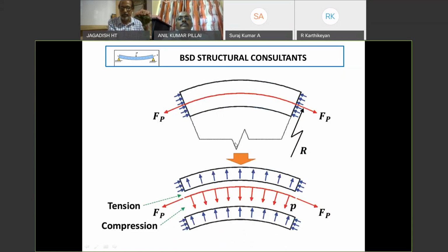Now, what improvement was taken? What was done to improve this? And what did we do later? The reactor building 1 dome was completely dismantled, up to the ring beam face. The ring beam was retained. Up to the ring beam, we completely dismantled it. For dismantling, we couldn't use any breaker. So we used core cutting machines, a chain of core cutting, and we completely removed the dome. Reinforcement, prestressing cable, sheathing, everything was removed. The dome was removed.